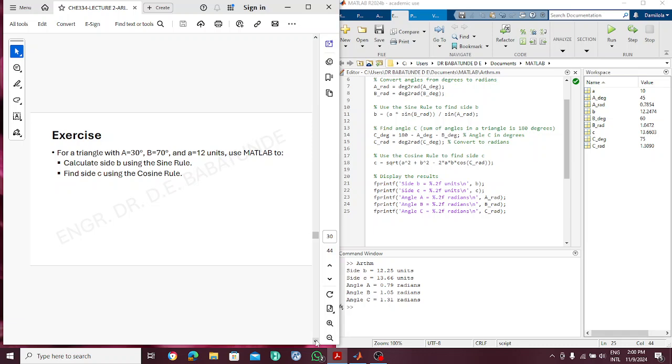If we know 2, then we can get the third one. So you make the necessary inferences, and you get the equations set up to solve for the unknowns. When you get it set up, you know what each means to MATLAB. Like we said, when you say sin or cos to MATLAB, it believes that what you are passing in is in radians. So you have to get that right, so that if you had your value in other units, you do the necessary conversion so that you and MATLAB are speaking the same language.